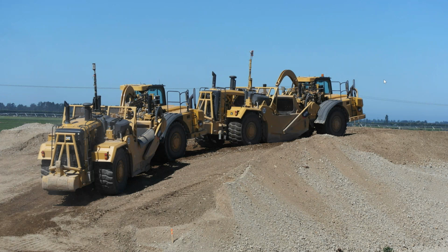Here is a scraping operation with tandem scrapers. See the second engine in the back, the first engine in the front. Here are our GPS monitors. This vehicle, see the apron is up, this banana beam is up, which in this lever has pushed the bowl into the soil, and this vehicle is filling. You can just make out a little bit of soil right here. It's being assisted by its friend, who is pushing on the rear to give it that little bit of extra horsepower that it needs in order to cut the soil.